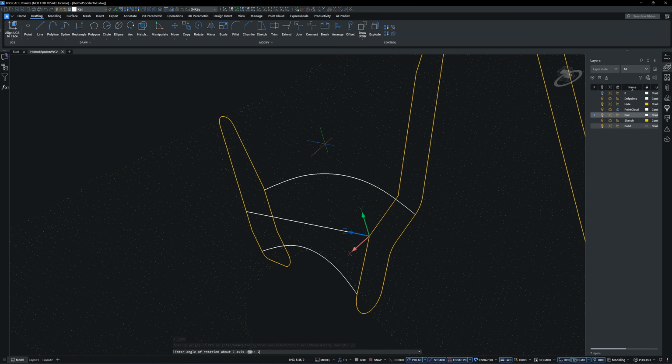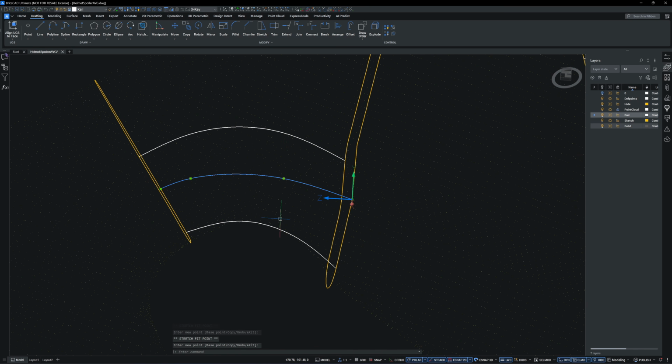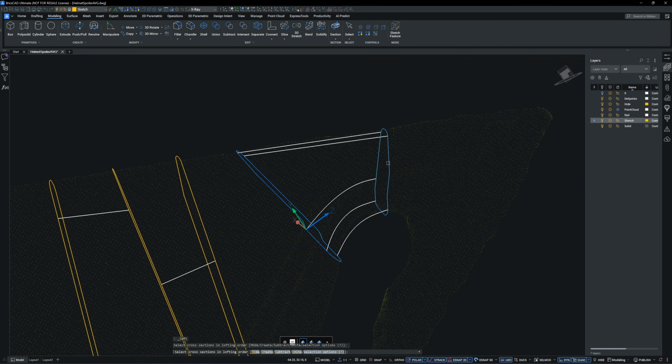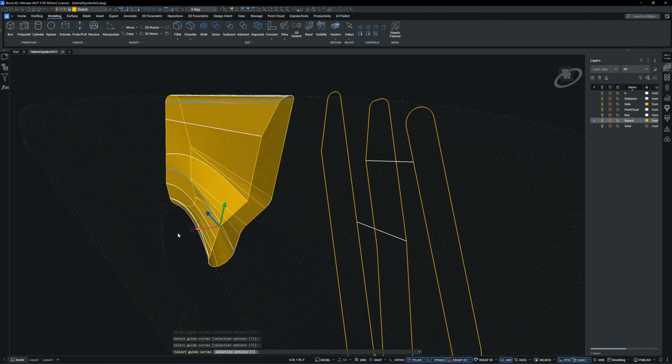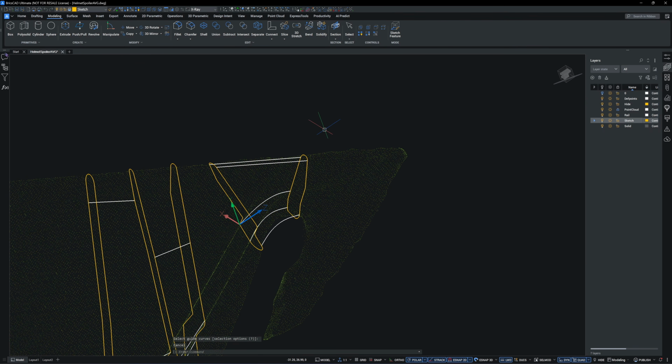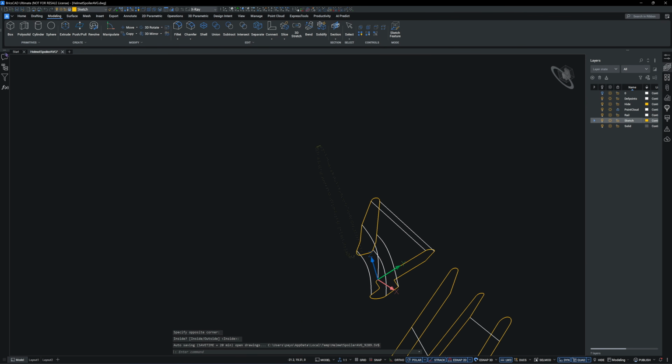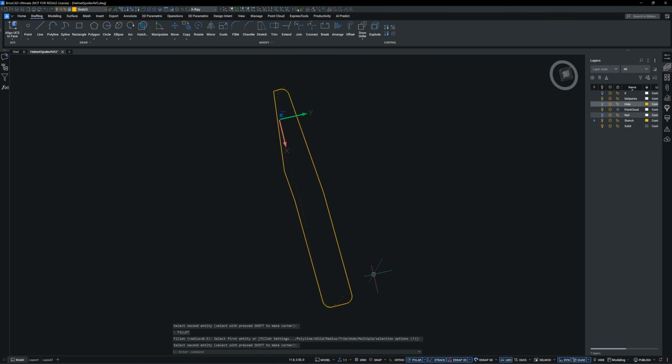Sometimes when you can't move the control point in the required direction, you can rotate the Z-axis by 10 to 45 degrees. The polar tracking will rotate along with it.